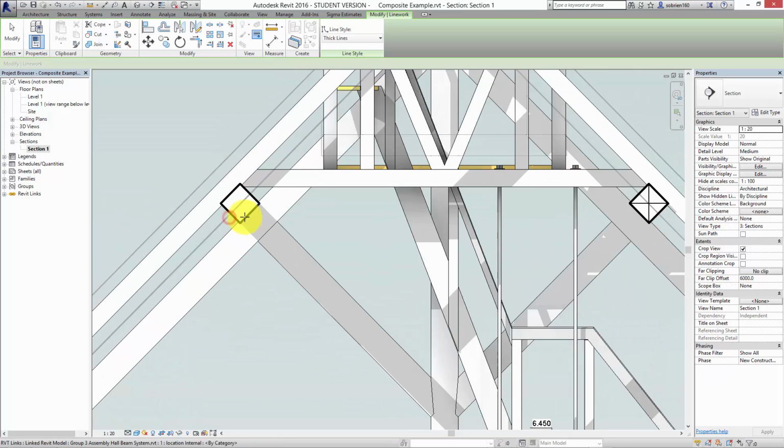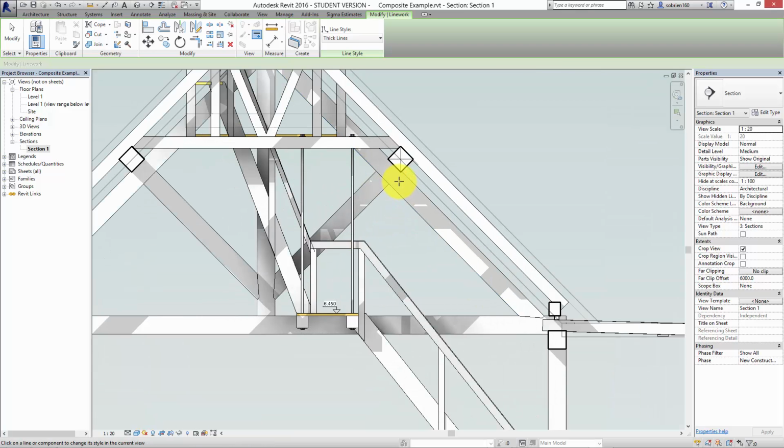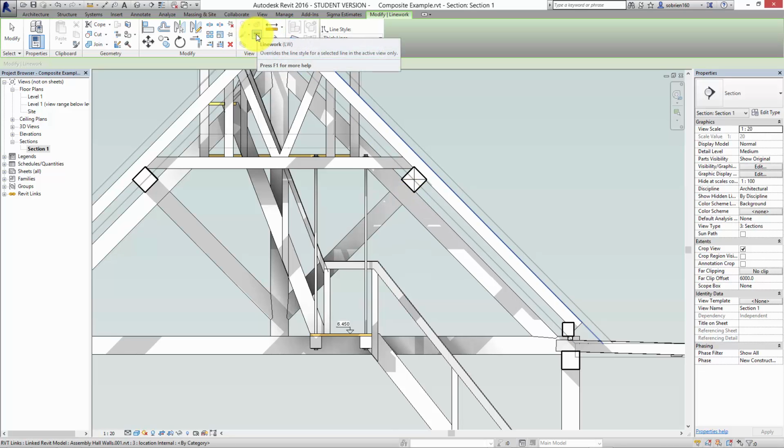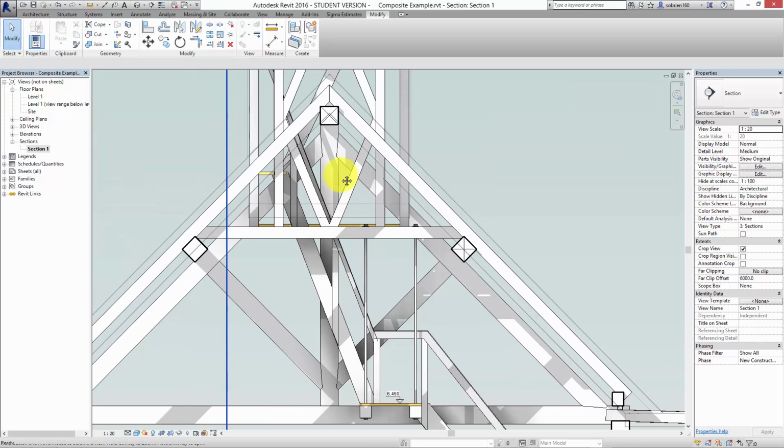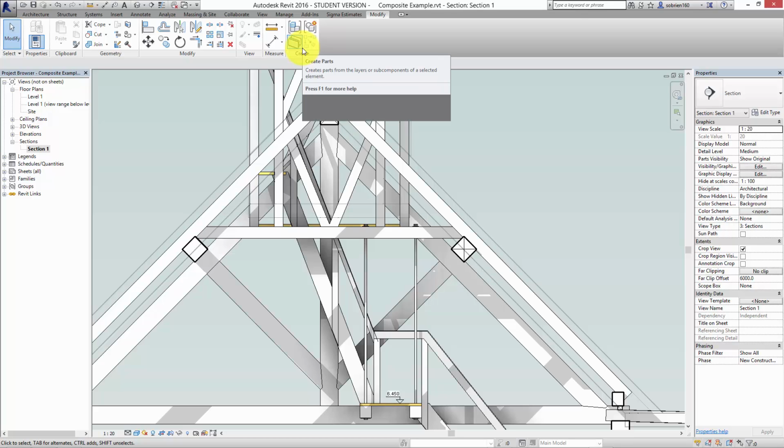So you can start to make it so that when the drawing is actually finished, the sectional elements are kind of punching out of the drawing, so it gives it a much more clear idea as to how the depth of the drawing is generated and so on. So that's this little button up here, or LW, which is, again, a good shortcut to just have at the tips of your fingers. All the shortcuts you can change to whatever you want as well, if you want to get into the menu. But you might as well use the basic ones that they have set up. But if you're used to using AutoCAD or something, you can change the shortcuts so that they're the same as the AutoCAD shortcuts if you want to.